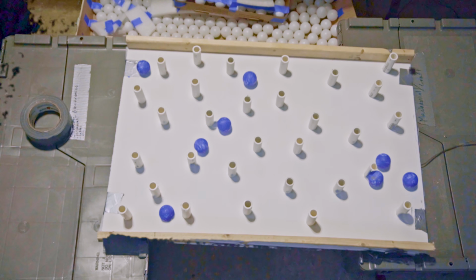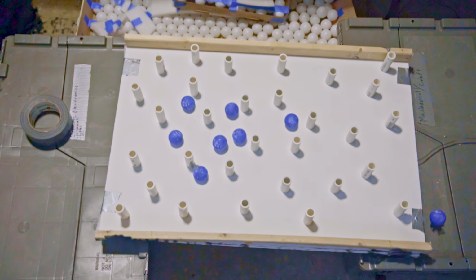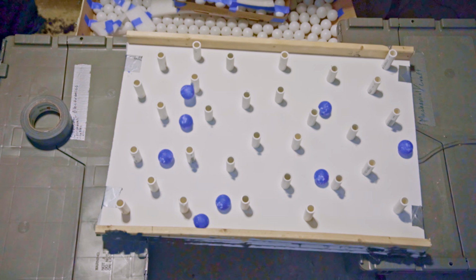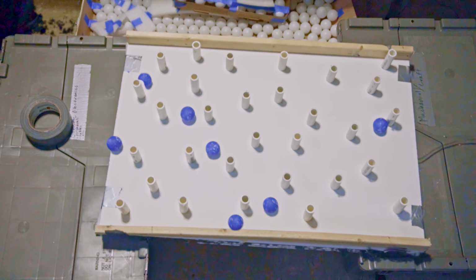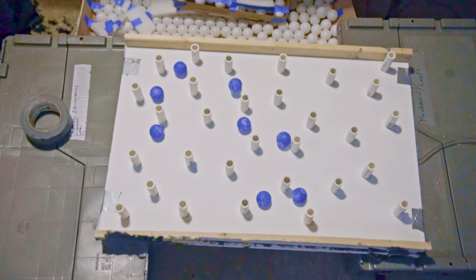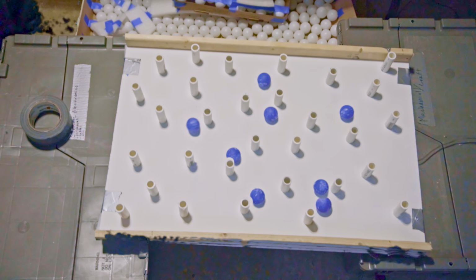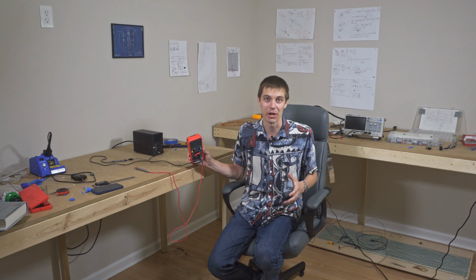When I said a minute ago that the average electron speed was only about a millimeter per second, I meant this average speed, including all of the backtracking. At any given instant, if 2 electrons are moving in a wire in opposite directions, but at the same speed, they basically cancel each other out. This is something that a multimeter can't detect. That's why we only talk about averages.